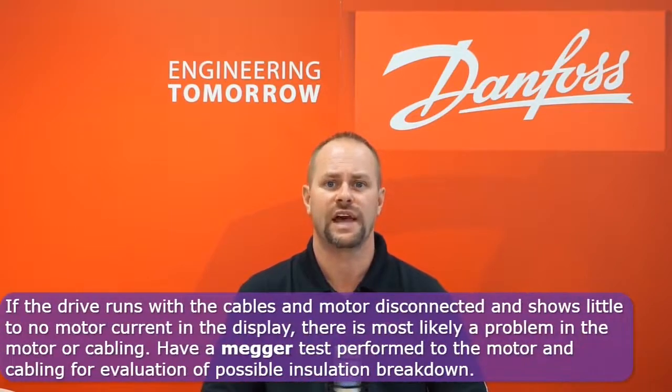Alternatively, the fault resets and the drive runs with no cable or motor connected to the output. When the drive receives a start command and a speed reference other than 0, the display will indicate that it is running, and there will be output voltage at the U, V, and W motor terminals. If everything appears normal while running open circuit, the problem is likely external to the drive and the cabling or motor itself. Use the appropriate tools, for example a megohmmeter, to evaluate the cable and motor insulation for breakdown.